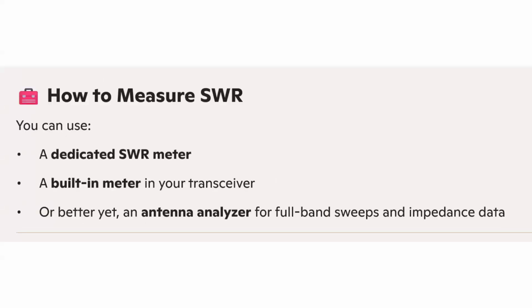All right, well, how to measure SWR? You could use a dedicated SWR meter. It's a popular accessory. Usually they're not very expensive. Or often your transceiver will have a built-in SWR meter. Or better yet, you can use the antenna analyzer for full band sweeps and impedance data.